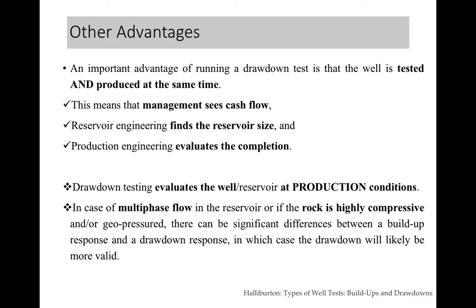Also, these data are very useful for reservoir engineers because they give the reservoir size. So we have put some calculations based on estimating the reservoir size out of this drawdown testing. We'll discuss that in some coming slides. Also, the production engineers evaluate the completion, and for completing the well, the data which comes from this type of test need to be gathered.